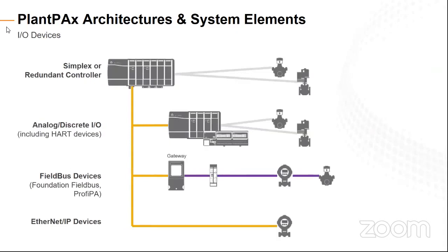System elements, so on the IO side of it. Obviously we're bringing in your standard information. Analog, discretes, control logix, and Flex are your defaults. Those are really, realistically, what we look to the most. Point IO and everything else that we have is available. All of those are case-by-case basis, depending on if you need redundant IO, if you need intrinsic safety, those types.